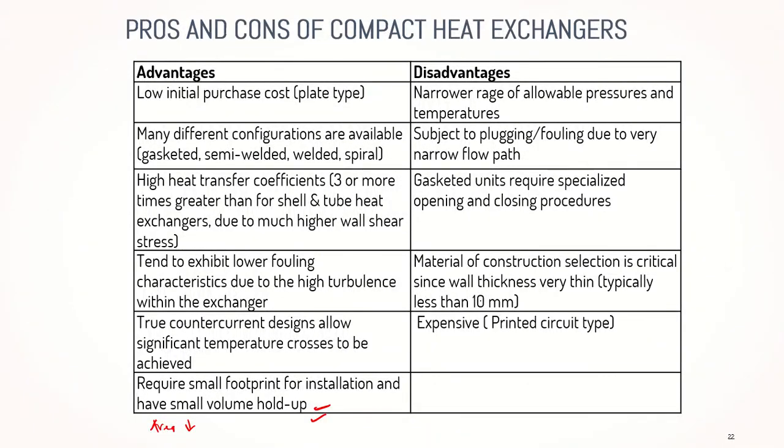However, if you wanted to use plate and frame, it's still okay, it's not that expensive. However, the problem is that it's subject to plugging or fouling due to the very narrow flow path. So you have to ensure that you clean it every now and then.